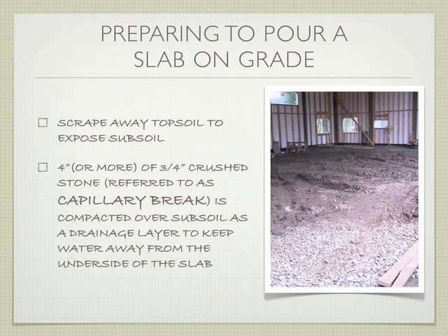If we instead have that rock layer underneath, which is what you have, if the dirt starts to swell and the water gets in there, it doesn't have any place to collect. It can drip out again and not come in contact with the slab. So there's no way for the ground to wick moisture up into your building. And this can be a big problem if you have a slab on grade and you have poor drainage around your building. I had a project that I worked on.